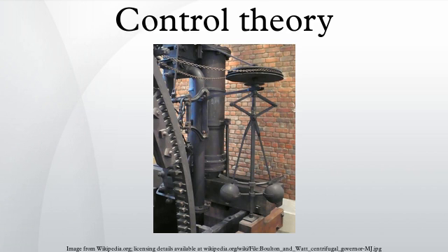The controller is the cruise control, the plant is the car, and the system is the car and the cruise control. The system output is the car's speed, and the control itself is the engine's throttle position, which determines how much power the engine generates.